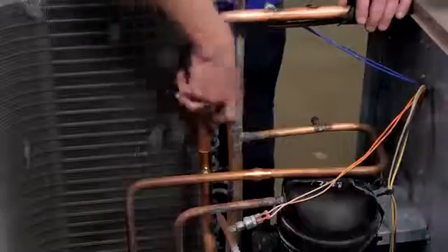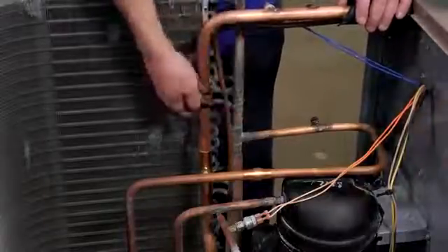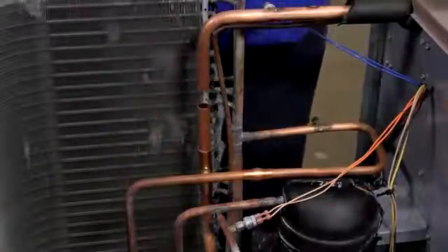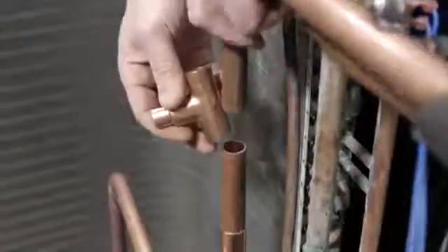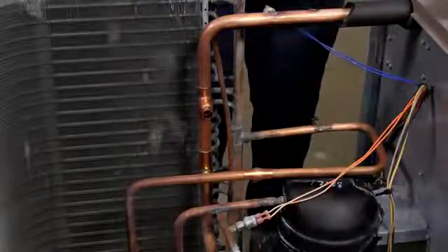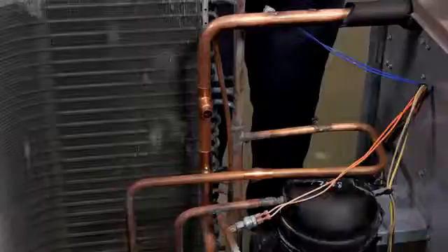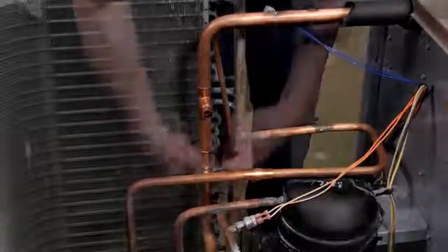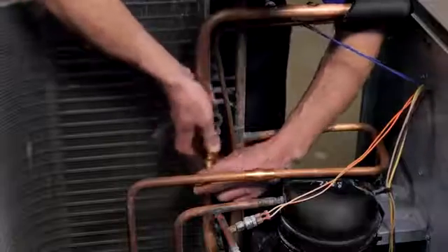The third T is cut into the suction line about 18 inches from the compressor inlet to leave room for the external equalizer and the sensing bulbs. This T into the suction line is position sensitive. The APR control mixed gas discharge line must enter the top of the suction line to prevent a possible oil trap. If you can't T into the top of the horizontal suction line, you can T into the vertical suction line. You will just need to create an inverted trap. The fourth T is cut into the suction line in between the mixed gas discharge T and the compressor.